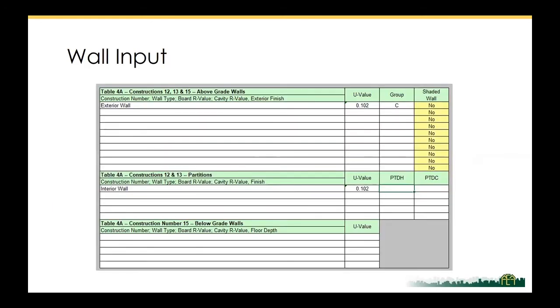And then you have your exterior wall, your U value, same as before, 0.12. Your interior wall is again R13, which is derated to R9.8 based off Energy Pro 7, which again is 0.102 for U value if you take the inverse.